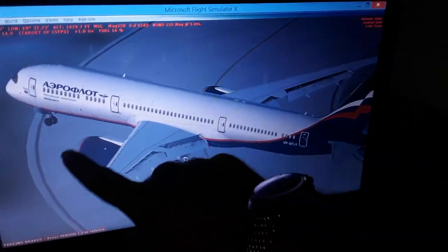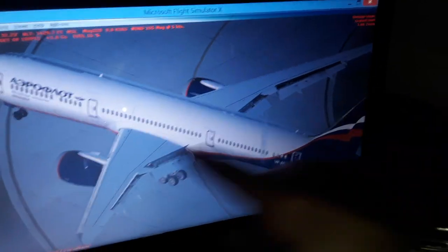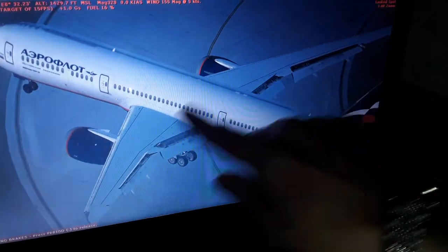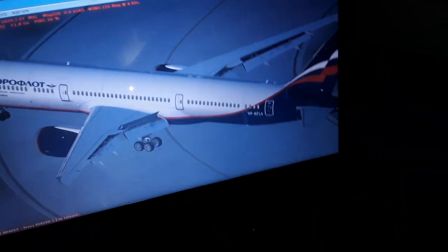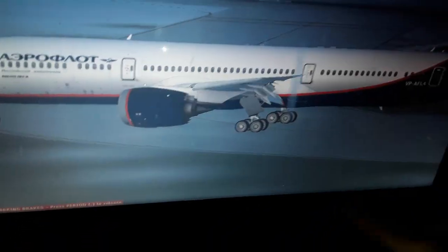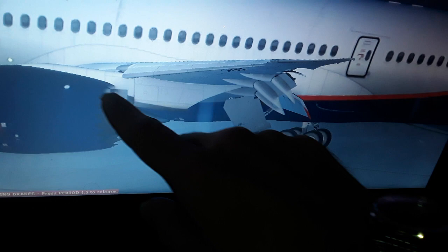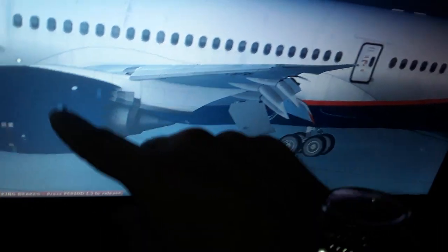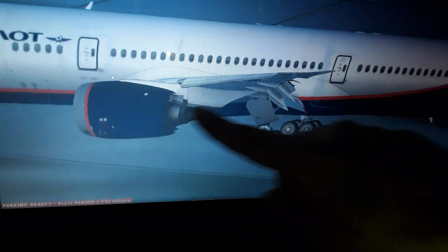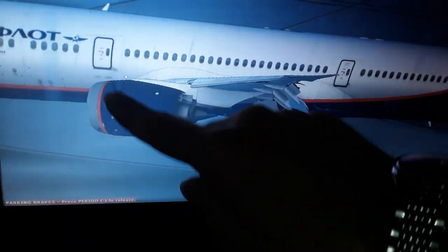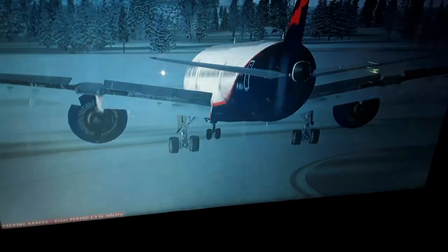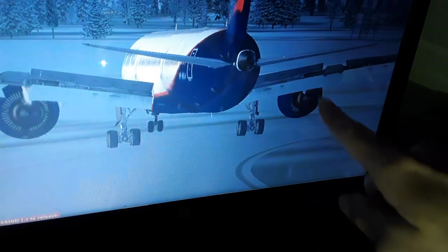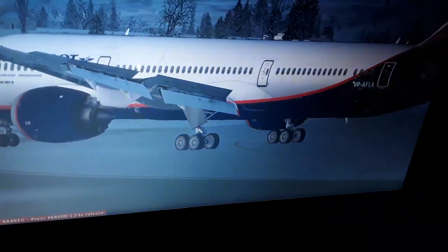So we have the engines here. You can see we have the left and the right wing fuel tank, the center tank. We have the fuel booster pumps over here and the high pressure fuel valves. Also the fuel supply for the engines is coming down here through this way, usually inside the combustion chamber. So we have the high pressure compressor turbine here, the jet engine, and the low pressure compressor turbine, the front fan. So you can see we have two flows. One is from the front fan and one is from the inner core of the high pressure compressor and turbine